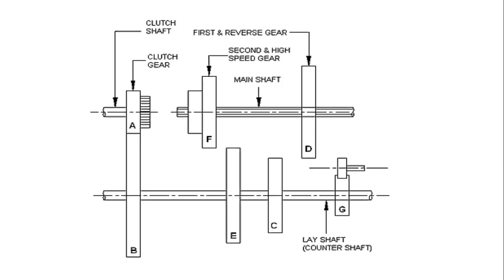So in the first gear what we have done, the input provided was 1000 RPM, is it not? And how much output are we getting? 200 RPM. So what are we doing? We are reducing the speed. So in case of your car or two-wheelers, whenever you are putting the first gear, the speed will be very less, but you will have a higher torque.